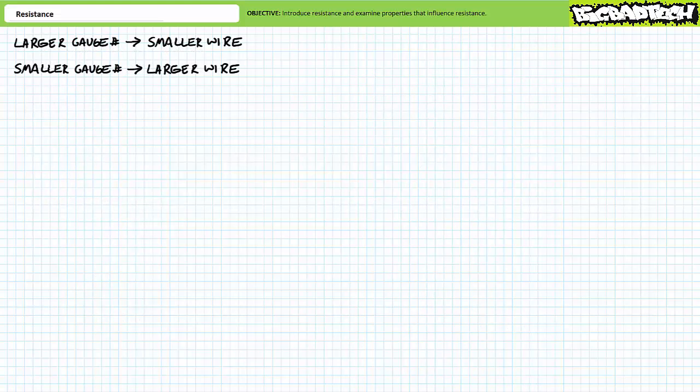Before we bring this lecture to a close, allow me to quickly introduce the American wire gauge and discuss how the resistance formula is associated with the American wire gauge. I was going to package a discussion of the American wire gauge into another separate lecture. However, it's too easy and so directly related to the same topic, my hopes are the discussion will be brief and to the point. The American wire gauge is a standard used to designate wire size, where the gauge number of a particular wire is inversely proportional to the size. Smaller gauge number means bigger wire. Larger gauge number means smaller wire.